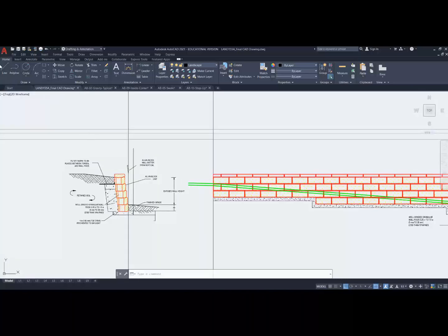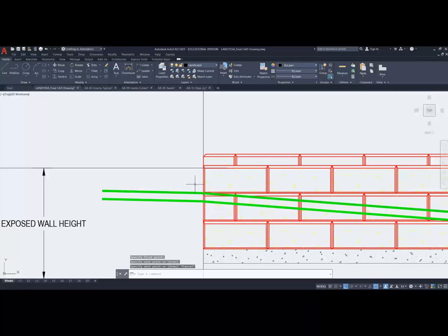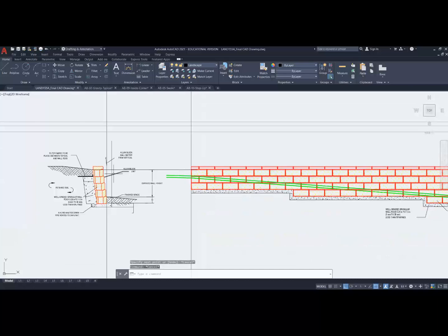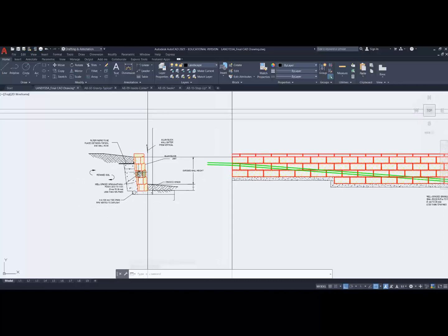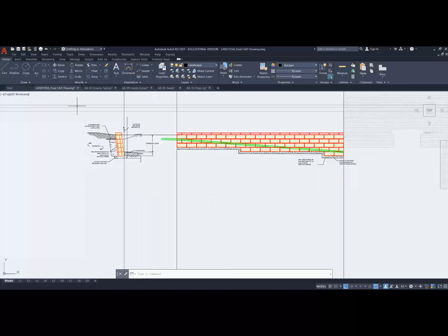Actually, the height of the wall, I drew incorrectly. From there across here. There's the height of that last bit of wall here. And what will happen is over this block, that grade is going to go from here to there. So there's going to be a significant slope at the end. So this is the view that I'm going to be drawing, my end view of that block. I'm going to see one full block and the cap in solid form, and then 2 blocks basically I'm going to see hidden. Remember, our elevations, the different elevations, are based on what is seen and what isn't seen.